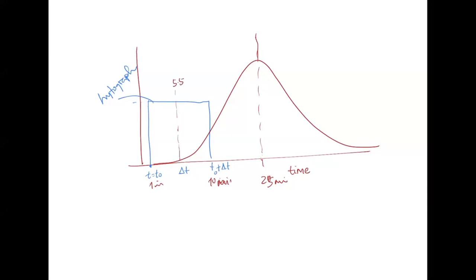And this is 25 minutes. So the lag time would be the difference between these: 25 minutes minus 5.5 minutes, which is 19.5 minutes. That means you have 19.5 minutes before the flooding will occur, or at least the peak flow will occur. Whether that will cause flooding or not depends on the system you have in place downstream. Does it make sense?